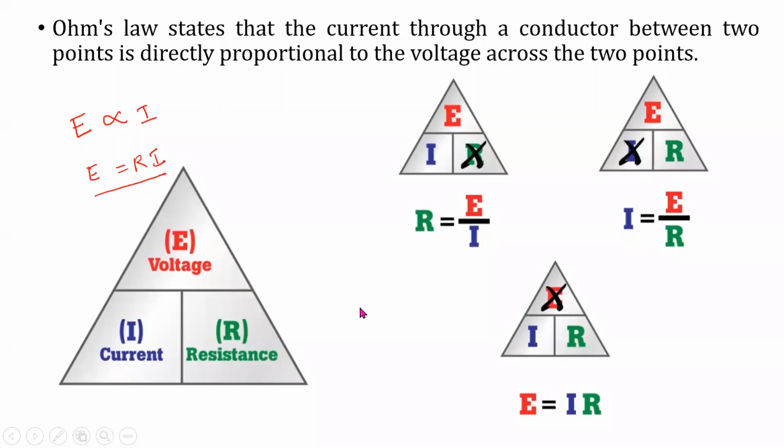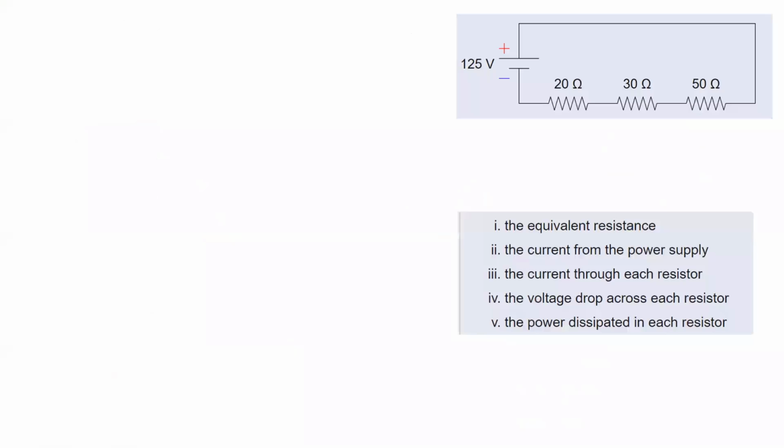Application of these formulas in a proper manner will give correct answers for the given problems. All right. Now consider the given problem. We solve the first point A, that is the first point, the equivalent resistance. How do we find the equivalent resistance of this given network? While finding equivalent resistance, you should not consider anything other than the resistors. Okay, so consider only 20, 30 and 50.